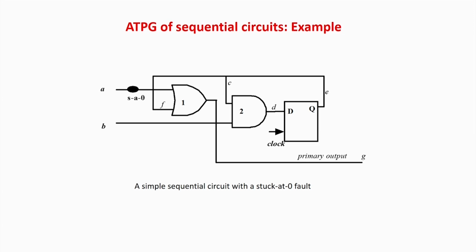Anyway, flip flops are interchangeable and the theory will remain the same, but for most of the implementations we generally use a D flip flop. And if you have forgotten your digital fundamentals, just a recap: a D flip flop will take the value from the input to the output on a clock edge. So, that is the idea. It is a simple D input and you will take the value to the output.